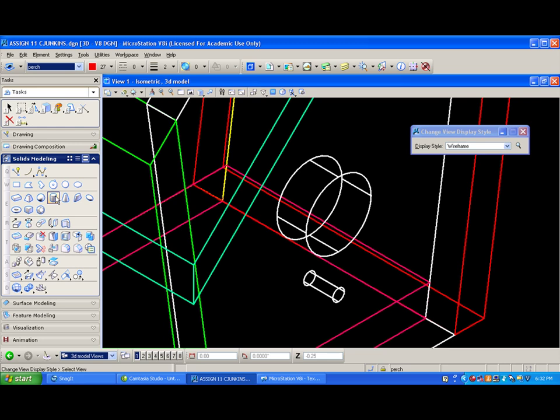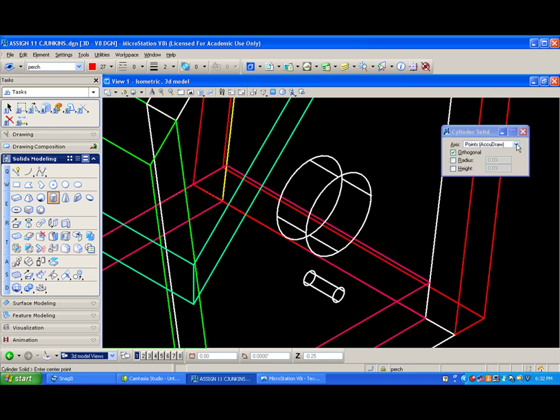We go to our cylinder tool, points AccuDraw, we'll go to the back end, snap to the edge of it. We don't have to key anything in. Bring this out. We know the thickness is 5/8. We probably want, we'll say 2 space 5/8. So it's 2 5/8 long.